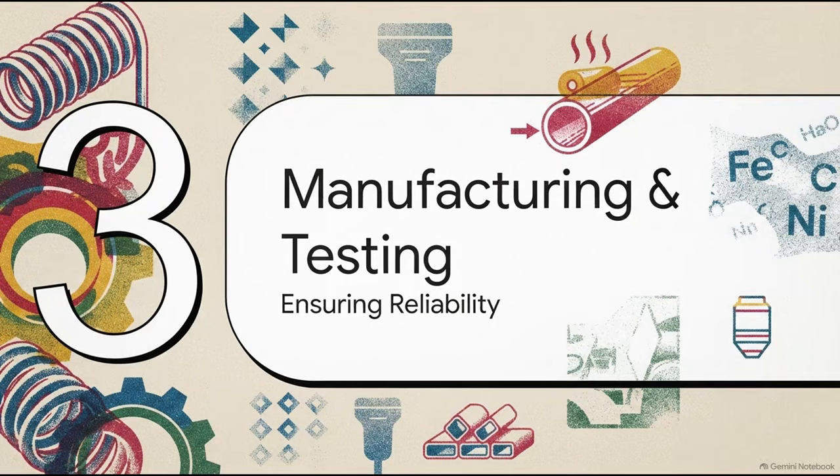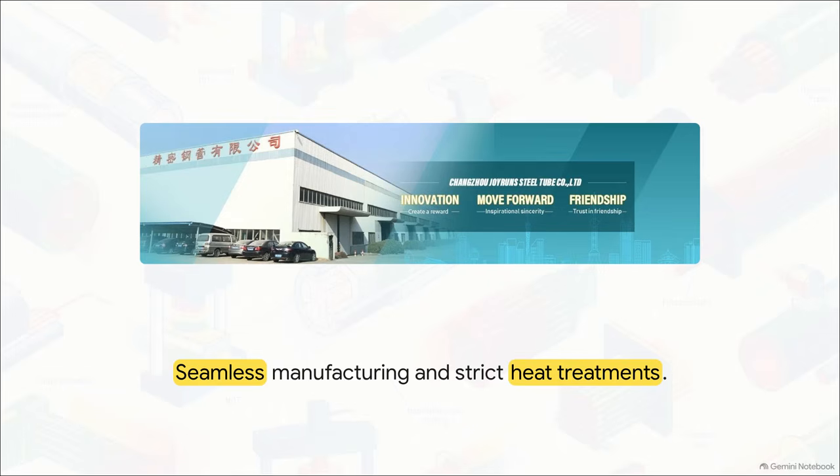But of course, a great chemical recipe means nothing if you don't bake it right, right? That brings us to Section 3, manufacturing and strict testing. Listen, the ASTM A213 standard leaves absolutely zero room for interpretation. The manufacturing process must be seamless. That means hot rolling or cold drawing solid steel billets. Again, no welding allowed.